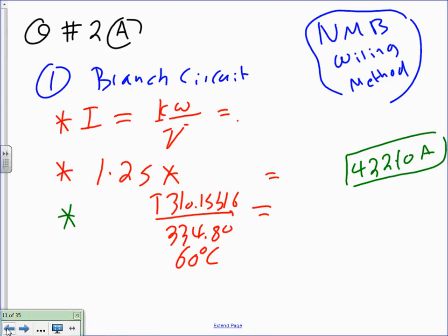Here's the math that you're going to do for this board. What was the kW in that board? 8. So you take the 8. Don't forget it's 1,000 divided by what's the voltage? 240. Give me the amp, will you? 33.3. Thank you, sir.